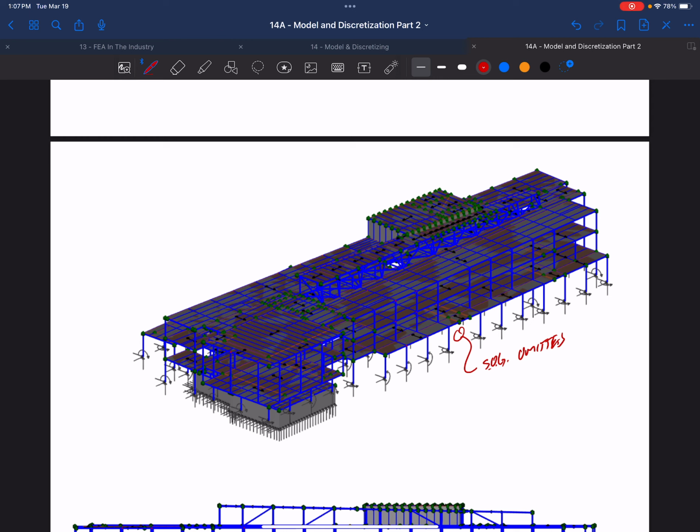We didn't include the foundation elements, right? The piers or the footings that each one of those steel columns were sitting on. We assumed that those were largely pinned with some rotational fixity, depending on if they were part of the moment frame or not. You can see this one's part of the moment frame. It has rotational stiffness if we were to push on the frame going in that direction. And that's what supports that edge of the building there, but that first story. But there are things that are omitted.